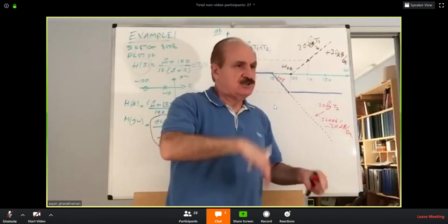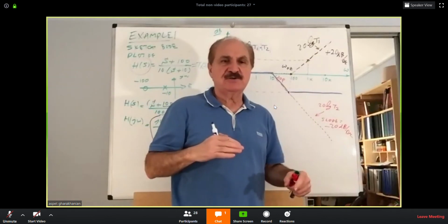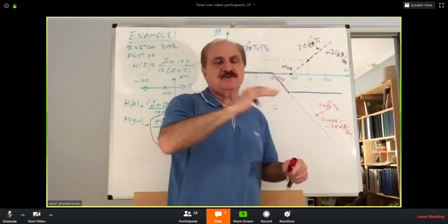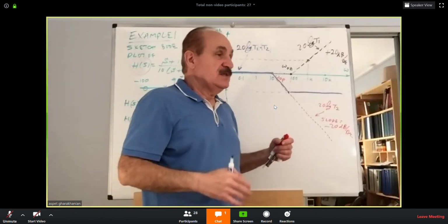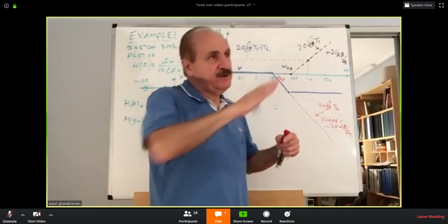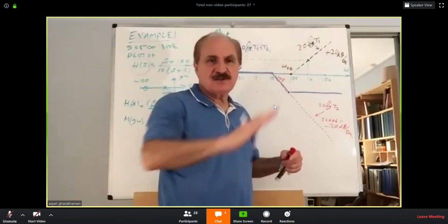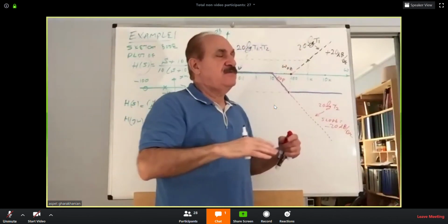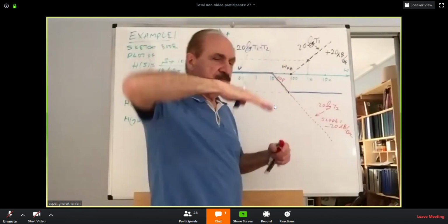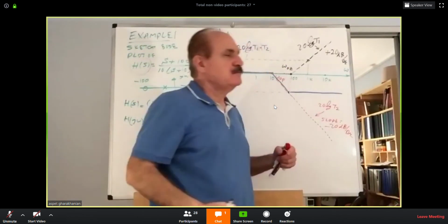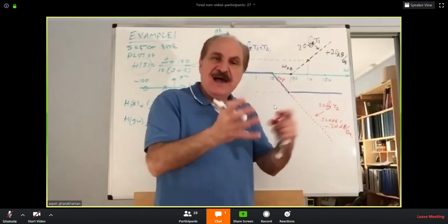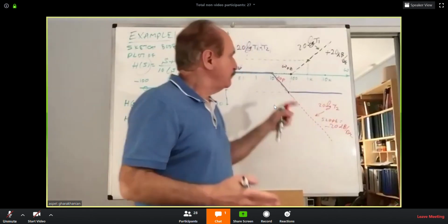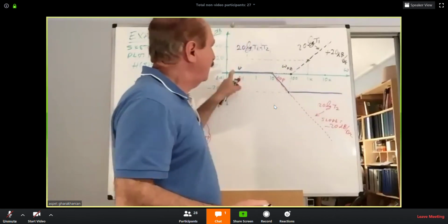You just construct the straight line approximation for zeros, 2 lines, or poles, again, 2 lines. And if it is a pole in the origin, it will be just a sloped line all the time, no breakpoint. If it is a 0, it will be slope up, pole slope down, no breakpoint. And you simply keep adding the lines together until you form the final solution.